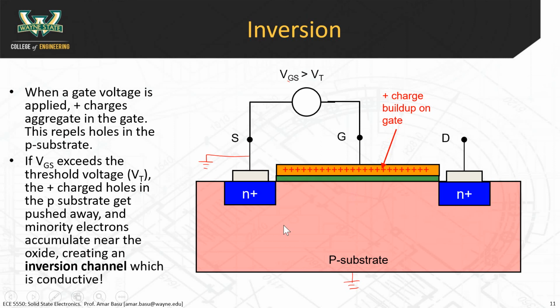All right, and I'm putting it this way so it's easier for you to understand. Now, if you think about capacitors, what are capacitors? A capacitor is a metal, okay, so you have a metal here. This is polysilicon or a metal. And then you have an insulator underneath that. And then you have another metal underneath that. So what we have here looks kind of like a capacitor. So they sometimes refer to this portion as an MOS capacitor. Metal, the orange, oxide, the green, and S, the semiconductor. MOS stands for metal oxide semiconductor.